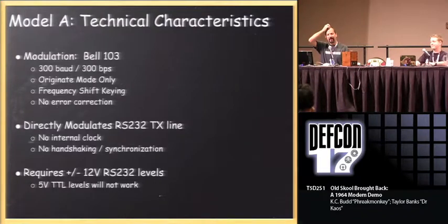And I learned a while back that programming PIC microcontrollers directly from a serial port works on hardwired UART serial ports and doesn't work on USB serial ports, and that's what inspired me to learn that, thankfully, so that when I started testing this thing, I didn't give up on it after the first thing I connected it to didn't work.